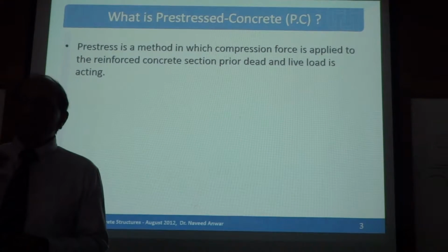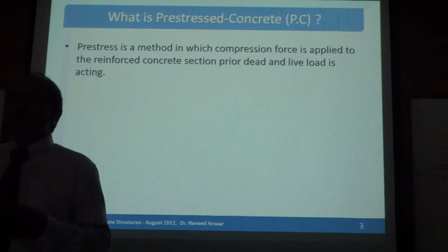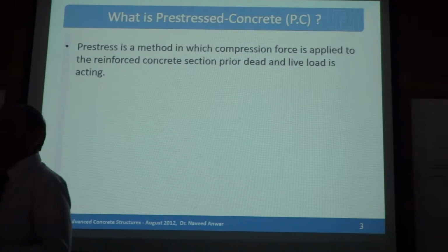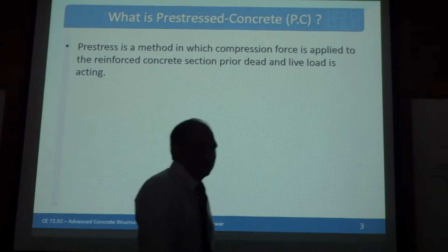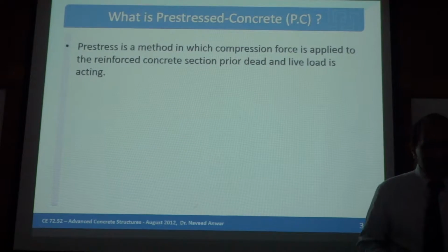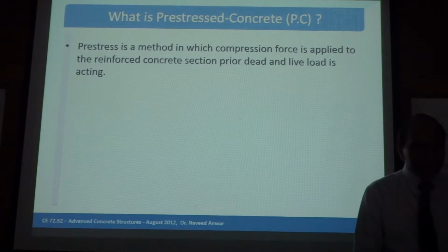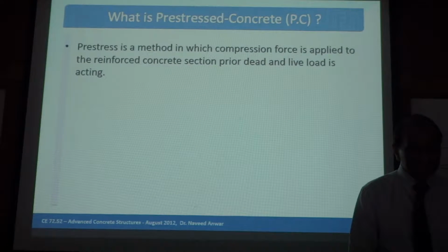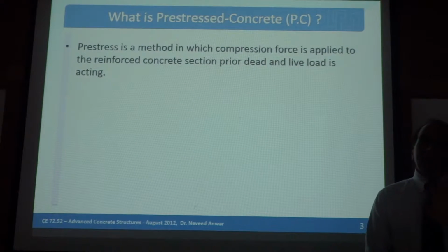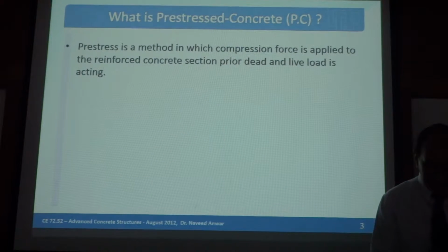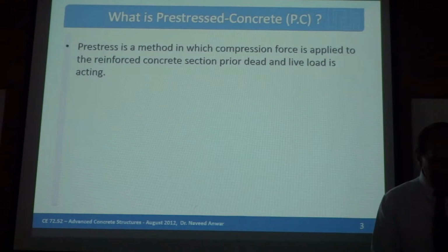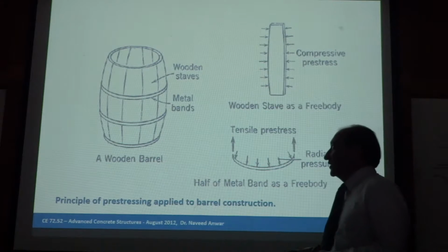Okay? And reduce the deflection. Why do you think the deflection is reduced? Because we have camber. Once the load is applied, it goes straight. Well, why is there a camber? Because the pre-stress makes it go up. Why does it go up? Because of the pre-tensioning. Okay, you understand the concept, but let's see why it really happens and what we can do about this, and whether we can make use of that in how many ways.